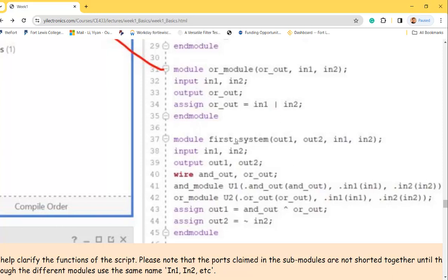It's just showing you a way to organize all the digital blocks. And maybe there's a bigger module to wrap up all these sub-modules called a big system. You can have another system called tiny system, whatever, right? So it's having different hierarchies of digital blocks, and eventually have everything included into one bigger digital block and call it test bench. So that's how you organize all the digital chips. This example shows you a really good example of putting all the different layers together and how to interconnect them. So this is a really important technique.